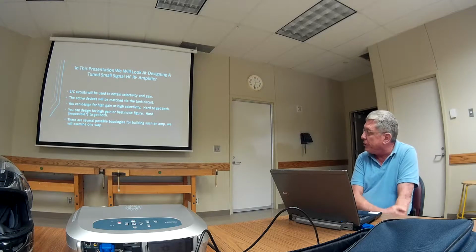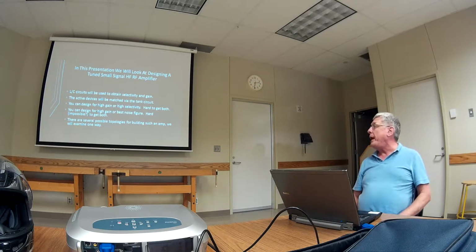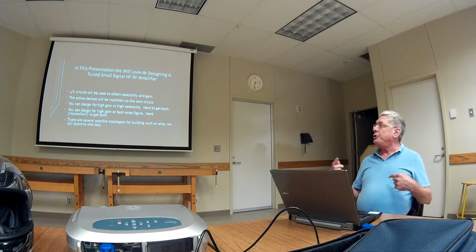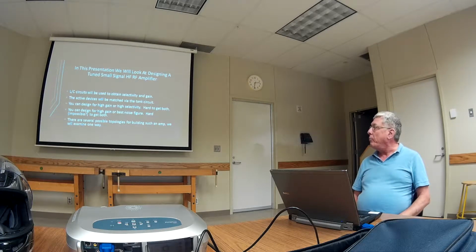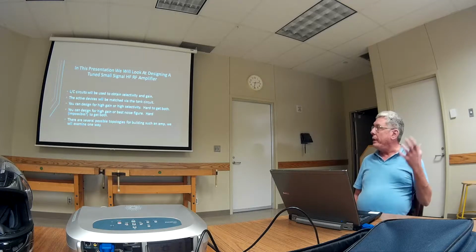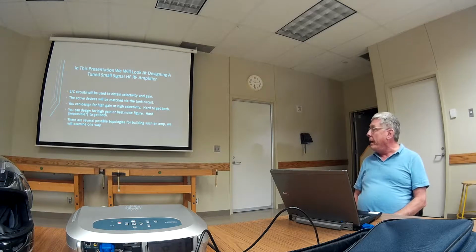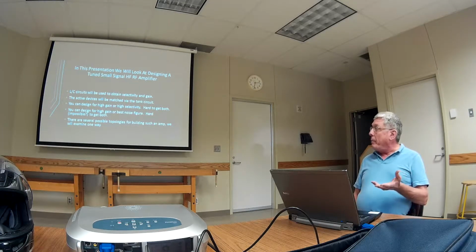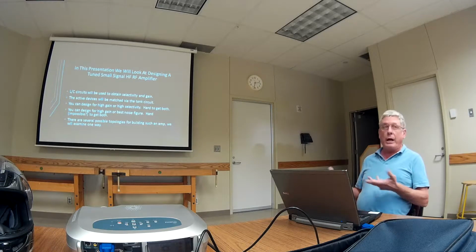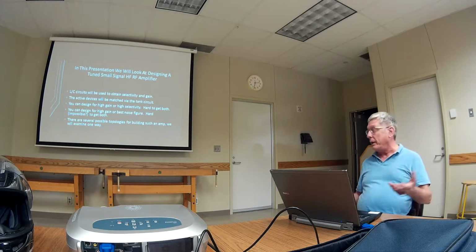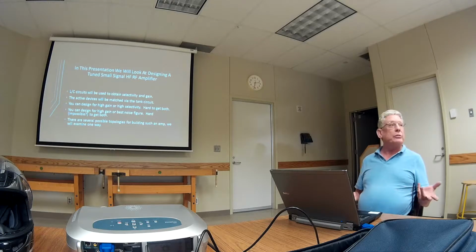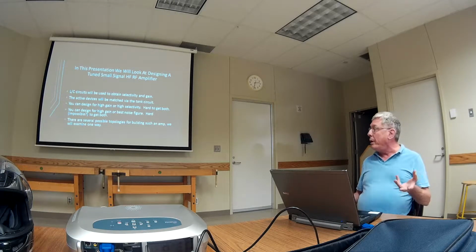We're going to use LC circuits to get some selectivity and some gain. We're going to try to match the active devices, the output impedance, the input impedance, get good gain. And like most things, you can't have your cake and eat it too, so you can either have a lot of gain and not a lot of selectivity, or you can have a lot of selectivity and not a lot of gain. You can also design maybe for best noise figure, but you're not going to get the best gain. I don't think that's ever going to happen. So everything's a compromise. You've got to decide what am I after, what do I want to do, and then concentrate on that.